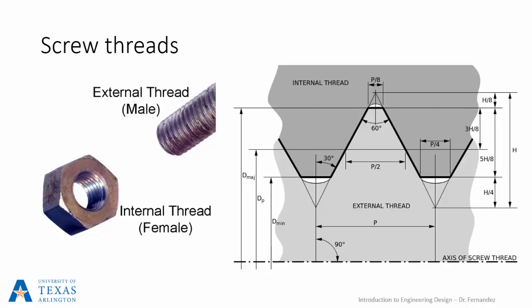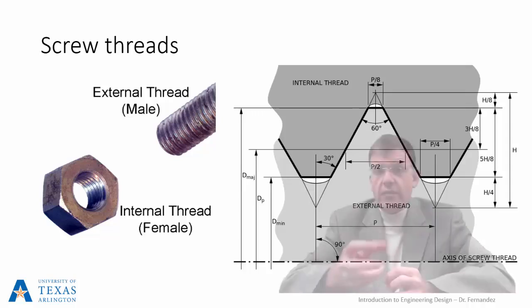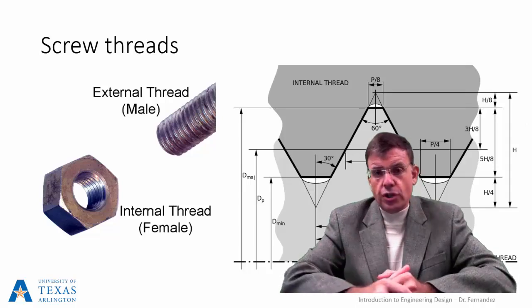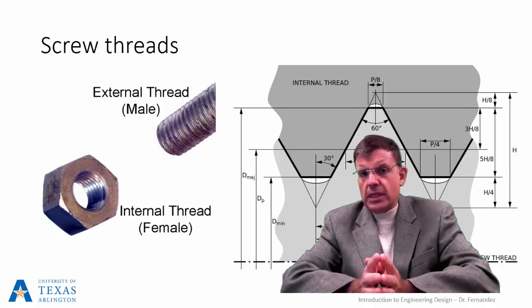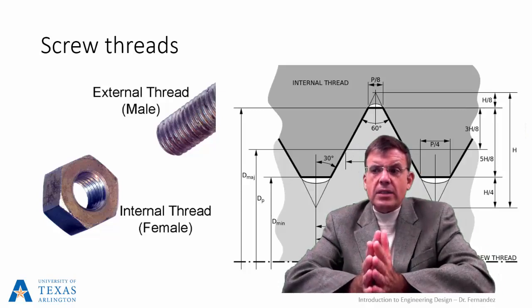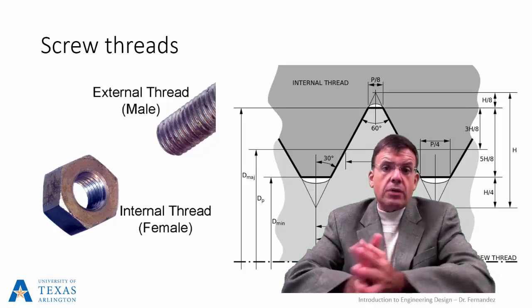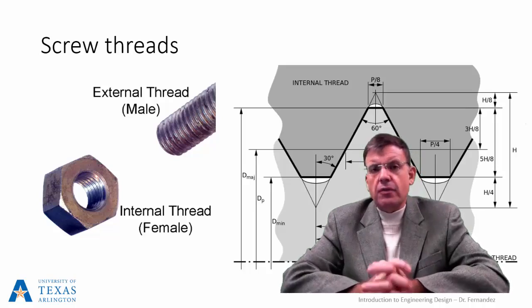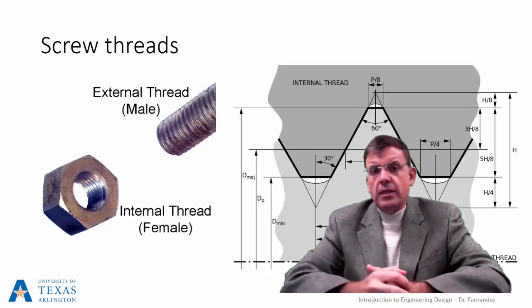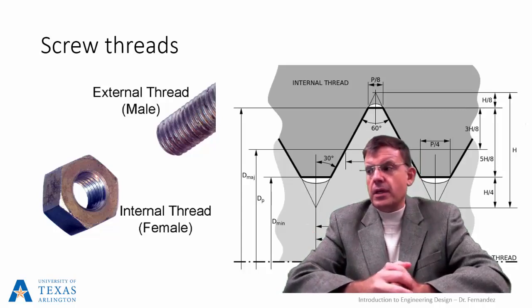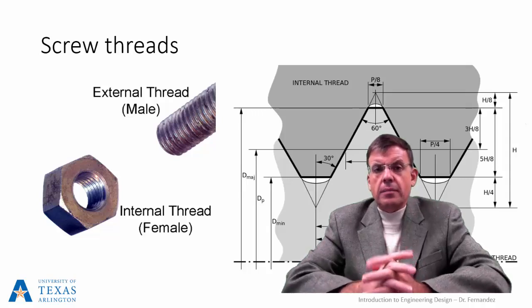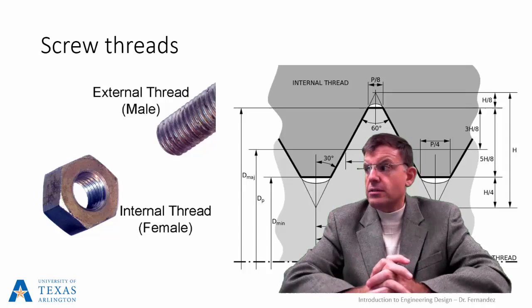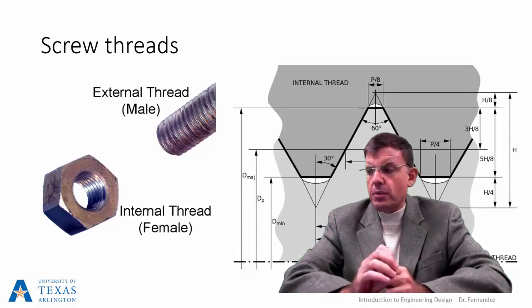Okay, so the pitch is very simply the distance between threads. It's also called the lead because that's exactly how much that particular fastener would advance with every turn. Okay. I'll also call your attention there to the angles. That there are many different types of threads. The ones that we're going to worry about the most, associated with common fasteners for assembly, fall under the so-called unified national standards. Okay, and those are going to have a 60-degree included angle in between the walls of the threads. Okay, so that's really the most important thing.